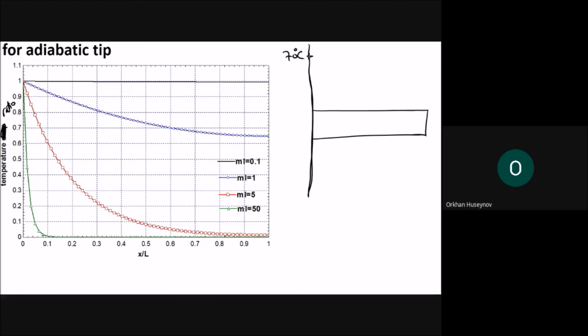Okay, and the base temperature drops in this manner, and at the end of the fin tip, for example, you have, let me not show it on the graph here because it will create confusion, so this one is the x-axis, and I will show the temperature versus the x-axis, and this is the end, and this one is L. At the beginning you start with T base. As you move along the fin, the temperature drops in that way, exponentially. It is also possible that the temperature drops in this way, and it is also possible that the temperature remains in that way.